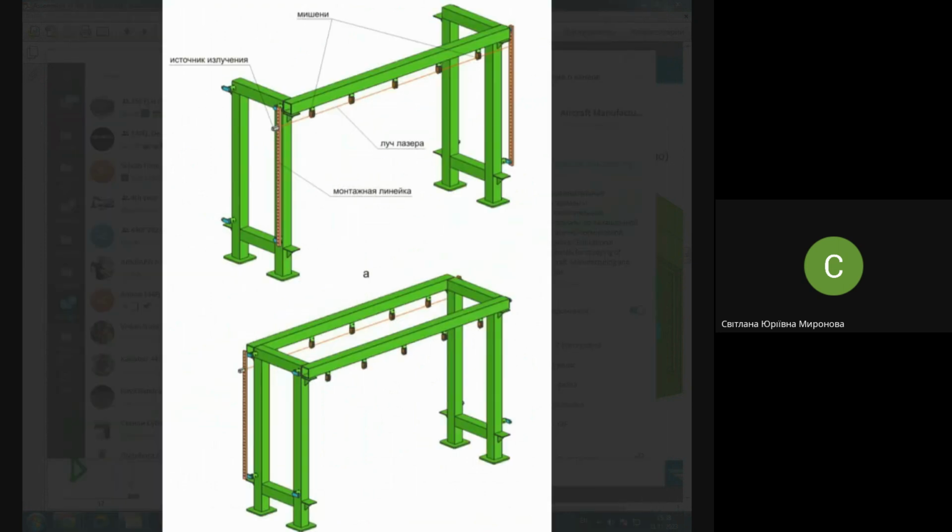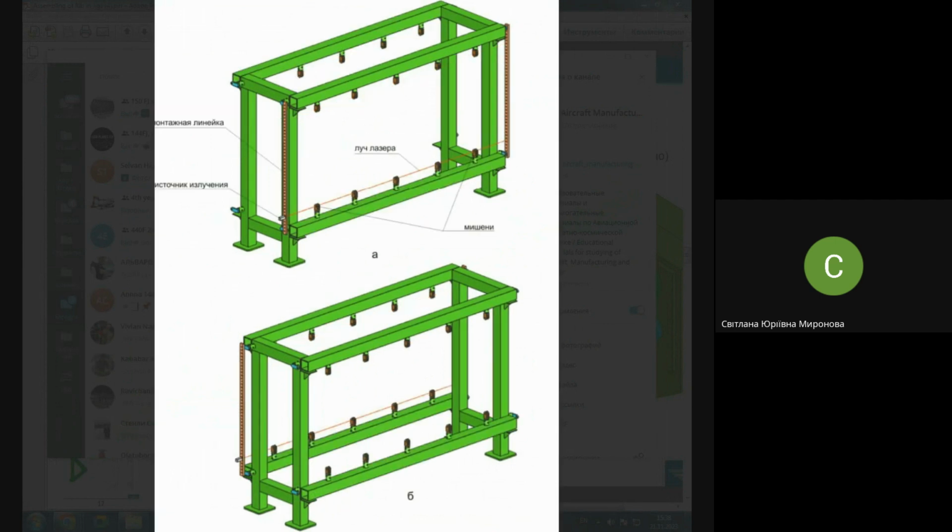Next, they measure the position of one beam with respect to another beam and do the same at the bottom, as you might see, by measuring rulers again, and optical devices. If necessary, they might insert a laser beam in order to trace whether all the holes are on the same axis and correspond to the next ruler or not, whether they deviate or not during mounting.